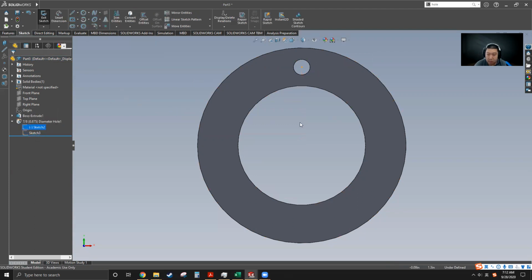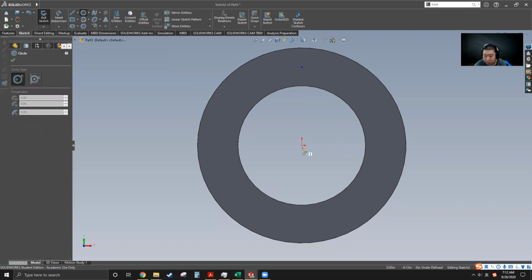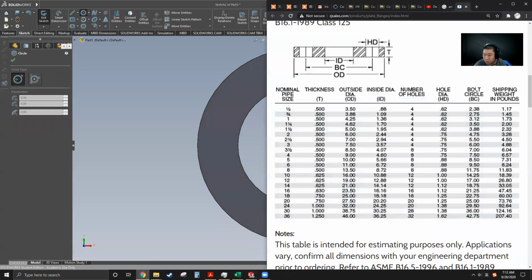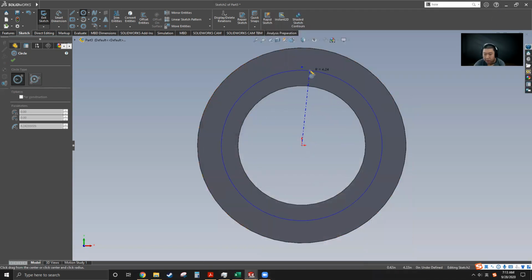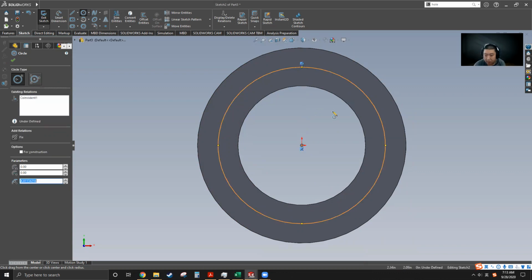So we're starting to get into the sketch and make a circle, because there is one parameter telling us what a bolt circle is, a BC. BC is 9.5. So we need to make this parameter happen and use it to control the location of the hole. So you do a circle, and now you see the circle can connect the origin of this circle with the hole, right? So that's what we want to do.